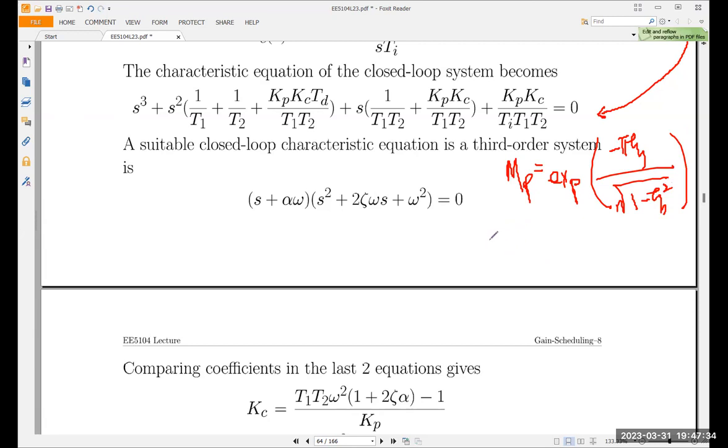All right, then settling time. So now if you say, I want my step response overshoot to be 10%, then you put 0.1 here, then you can calculate what is zeta. That's standard control engineering. So you get the value of zeta, you put it here.